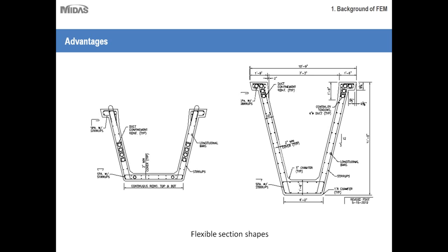And if you are doing the design check and planning to optimize the weight of the structure, you can consider different alternates also. Based on the type of bridge, different span lengths and all, you can come up with a more optimal section rather than being limited to the conventional I section that we are using.